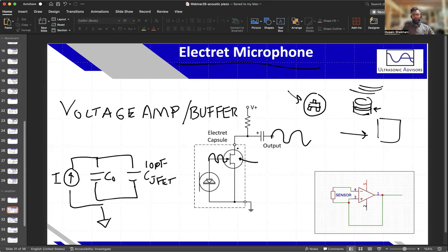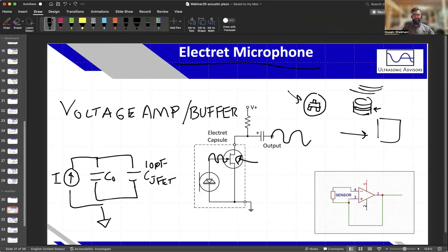Rather, this forms basically a small amplifier, which I think I may have discussed at one point, but I can discuss how this works because it's kind of interesting in comparison to what we just throw in an op amp. Getting discrete is very interesting sometimes. So it provides a voltage buffer. This has a variable resistance according to the voltage applied at its gate. And similar to a MOSFET, it has a small capacitance associated with the gate, but it's constant, and you can put this very close because the JFET is not mounted inside your laptop. It's at the back side of the microphone, as close as you can get, to eliminate noise and reduce as much stray circuit component as possible.